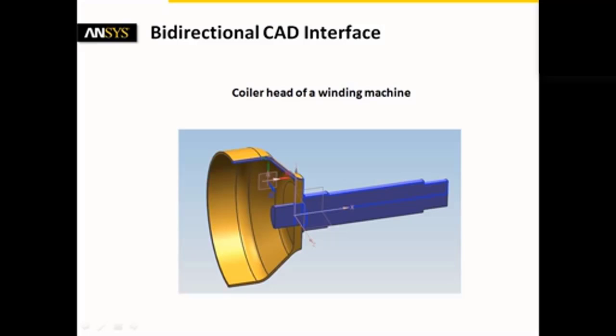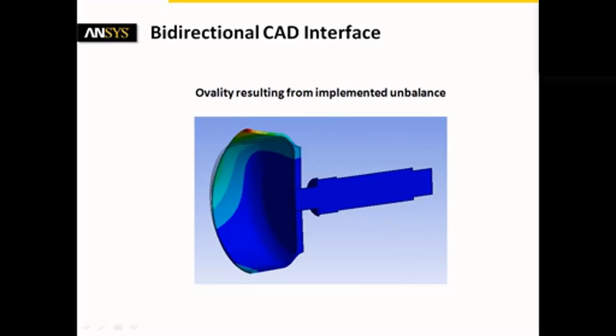The design development is driven by two competing goals. On the one hand, the drum weight should be minimized. On the other hand, the dimensional stability with respect to ovality resulting from imbalances has to be maximized. Those aims support resource savings, faster run-up and run-down times, as well as process reliability regarding adherence to close tolerances.